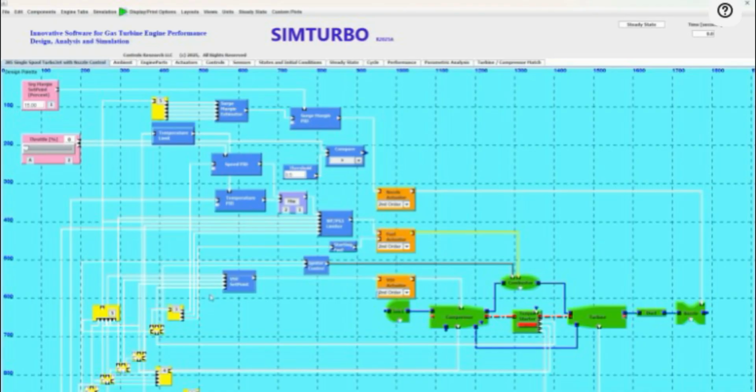properly lit. The signals for the necessary engine parameters are measured and transmitted to the control by the sensor components, represented in yellow. The necessary sensors include measurements of the turbine shaft speed, the compressor inlet temperature, the compressor inlet and exit temperatures, and the turbine exit temperature.